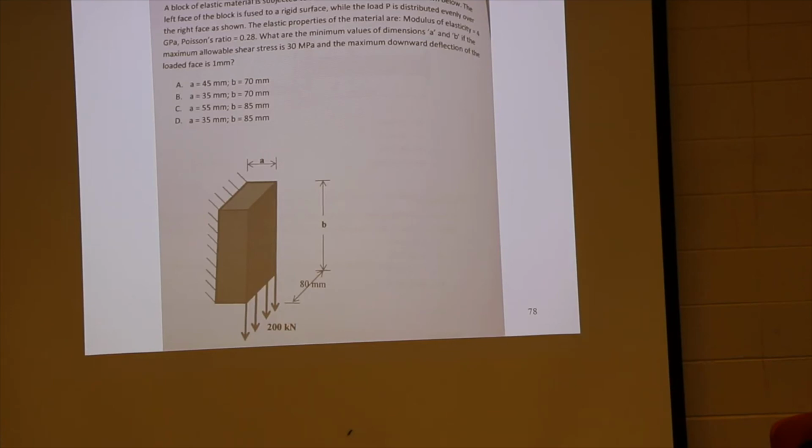Here, you have 2 criteria to satisfy: shear stress and shear strain. Do you have G? You don't. You have E and mu. Use the formula to get G from E and mu. Then start working. This problem is not very hard. It just took a ton of text to explain. But it's not hard at all, really.